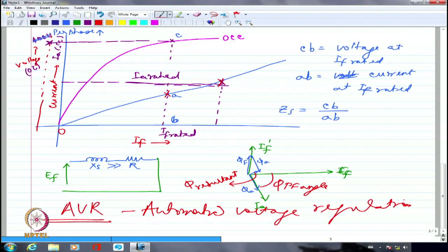Whereas here, if I try to measure the field current, that is not going to really give me an index of what is the impedance or the current that would have been drawn by my armature. They are disconnected circuits completely. And you can't even say the current carried by the armature is going to get reflected onto the field. Not at all. It absolutely depends upon what is the amount of load that you have connected. The current will only depend upon that. And to supply that load, I should have given a sufficient amount of mechanical power from the prime mover. That's all it is related to. The field is only working as a wire media. It's a facilitator. It is definitely not giving any resources. It is only a facilitator. So, you can't really take the field current as the current which would reflect on the impedance of the armature.